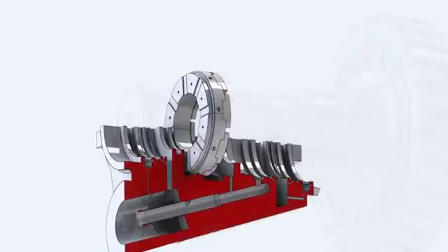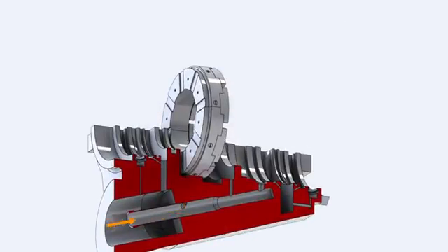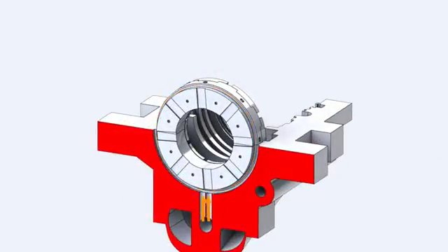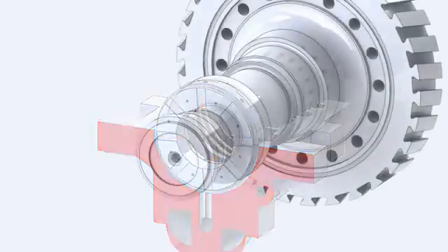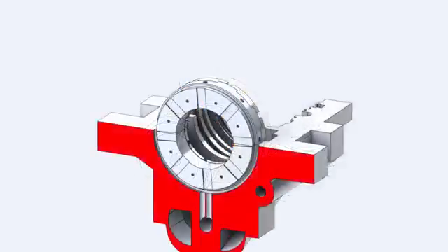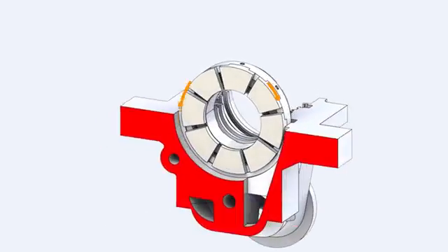For lubrication, oil is supplied through the oil feed pipe to two ports in the lower bearing housing, where the oil flows into the annular space around the base ring. Then, oil flows through grooves machined on the backside of the base ring to the bearing cavity, where it is carried by the pumping action of the thrust runner to the entire bearing surfaces. Oil exits at the pad's periphery to the thrust bearing drain cavity down to the lube oil drain piping.